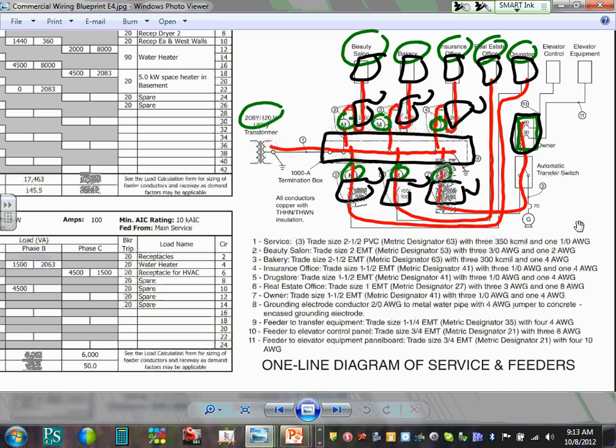Can you guys see how the system is put together? Everything black is a standalone system, and the meter is a separate enclosure. Here's a meter, right? So how many enclosures? I have 1 enclosure for the gutter, 1 for the meter, 1 for the fuse disconnect, and 1 for the panel, for every system. Can I have a thumbs up? You fully understand? Okay, so that's why it's nice starting from the end.